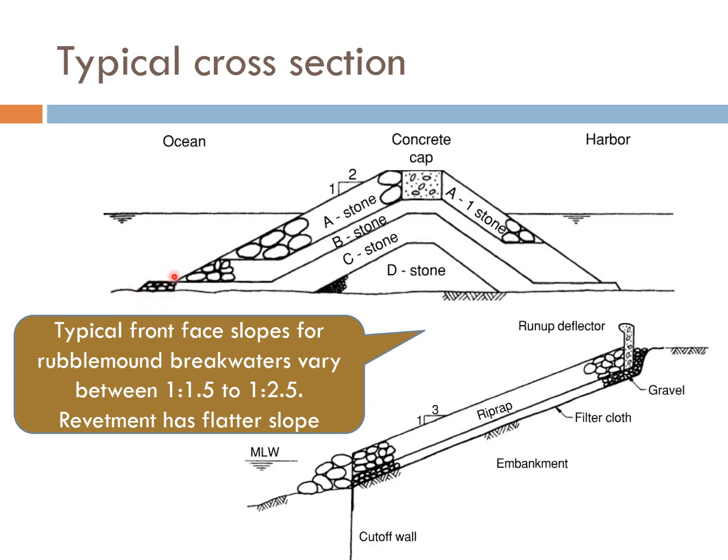Toe protection will be required, and once these are all determined, we will then get the overall idea of how the cross section looks like, the overall size of the entire breakwater, and thus the loading imposed on the seabed to find out whether the bearing capacity of the proposed location is sufficient or not.